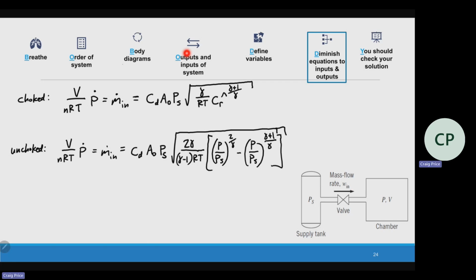That's kind of a reason why I stay a little bit away from this. Hydraulic, especially if I'm dealing with incompressible, it's pretty nice. I have a linear relationship. Once I get to pneumatics, not only am I seeing a lot more turbulent flow, it's got to be turbulent, it's a gas, right? But we're also dealing with temperature, we're dealing with all the different gas constants, everything like that. So there's a lot of variables going on here.